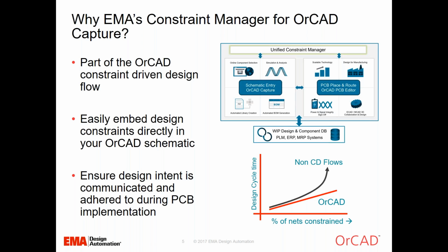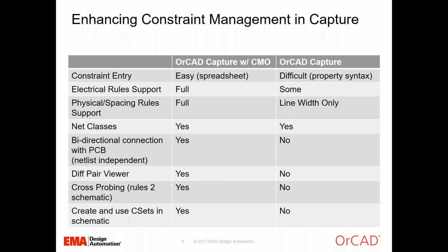Okay, so why EMA's Constraint Manager for OrCAD Capture? It is an integral part of the OrCAD constraint-driven flow. It allows the engineer to easily embed constraints directly into the OrCAD Capture schematic, which will then be transferred directly into the Allegro or OrCAD PCB Editor board files. This eliminates the need for paper documents and checking to make sure that the engineer's intent was understood and implemented by the layout designer.